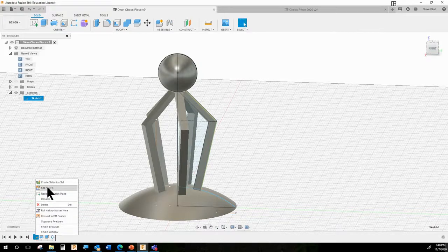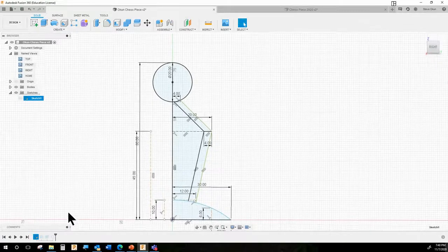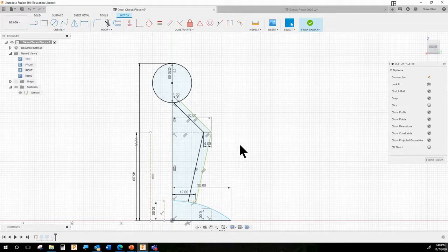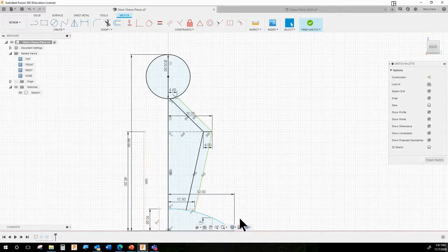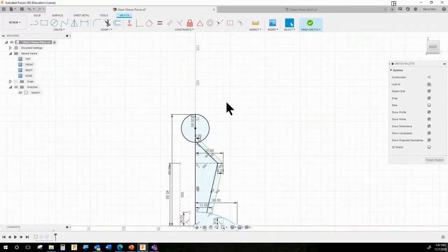So we are going to right click on that original sketch and say edit sketch. Again, remember, you can't make multiple sketches. These all need to work together unless you want sketches for some reason to be separated from each other. What our client has told us is that they want it to be 10 millimeters in and 55 millimeters high where that first knob is. So once again, we're not going to use squares to count. We are going to use